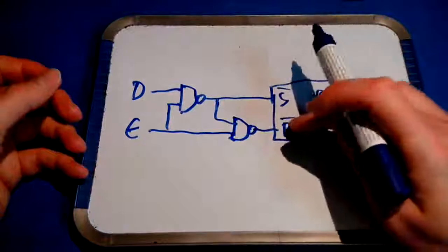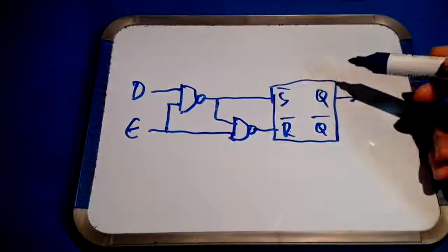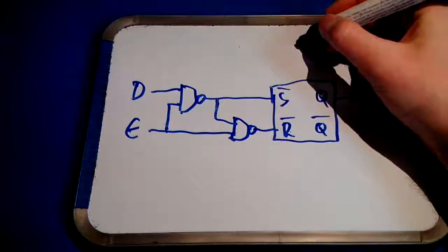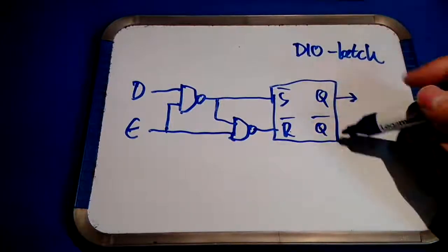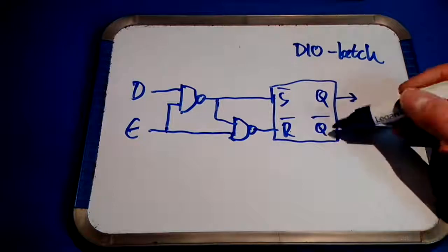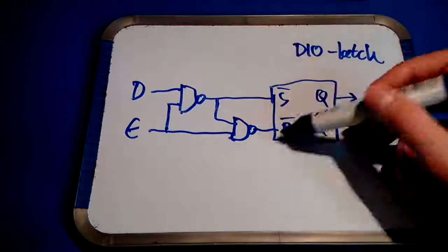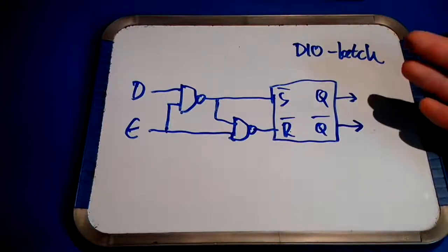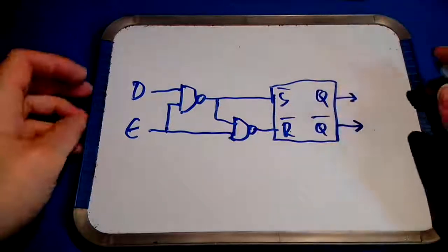Now, in the previous video, when we talked about the 8-bit latch that you saw just now, or rather 1/8 of that board, we drew a similar circuit. The difference between the DIO latch in this video and the 8-bit latch in the other video is that in this case we have an inverted output Q overbar in addition to Q, and this latch does not have a clear, while the 8-bit latch had a clear to reset it to the initial CPU state, because that module was used to start executing at program address 0. In the case of the DIO latch, we don't need that.